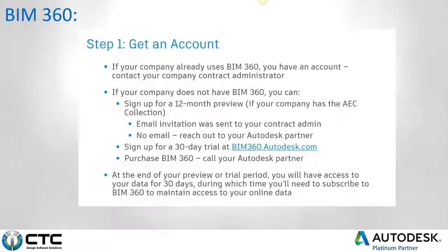Well, if your company already has BIM 360, contact your contract admin to gain rights to it. You don't personally have to be the contract admin to the entire account, but inside BIM 360, I can make projects. And if I have my contract admin assign me rights to a project as an administrator for just that one project, I can then make subfolders underneath that project folder for all of my Infraworks models. And then from there, if I want to invite people, I can do that.